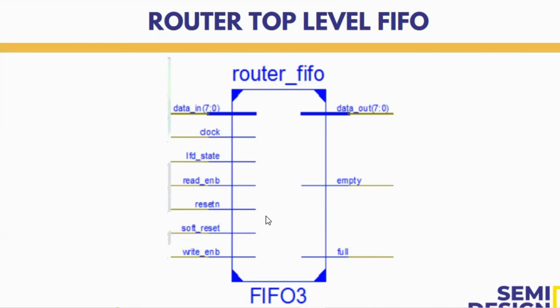When that will happen is, you have the data stored in the FIFO. Actually, FIFO size is 16x9, which means FIFO will have 16 different fields, from 0 to 15. It can hold 16 values, and each field will have 9 bits. So how will it accommodate 9 bits, when here you are sharing only 8-bit data, right?